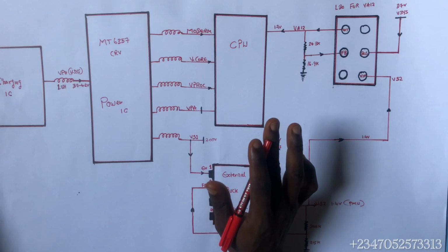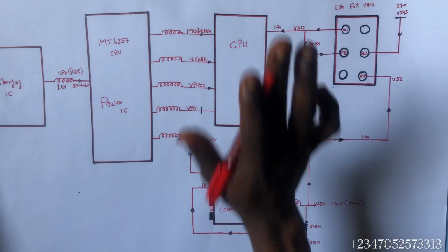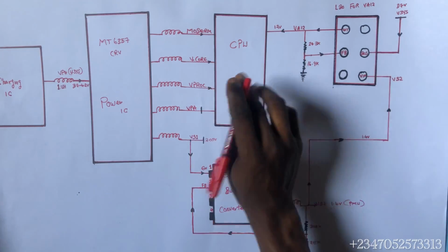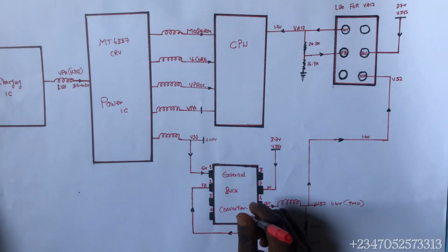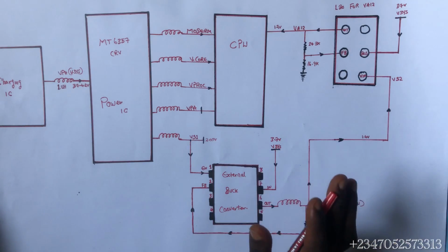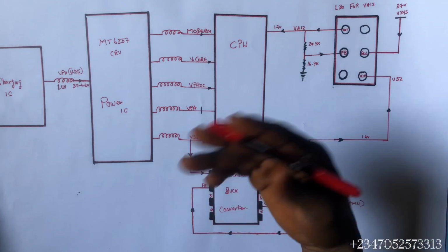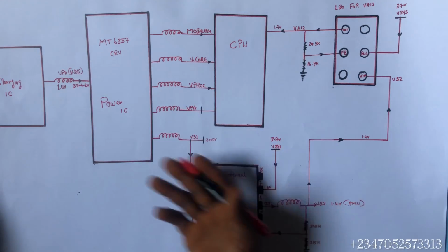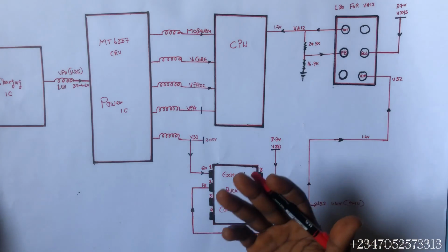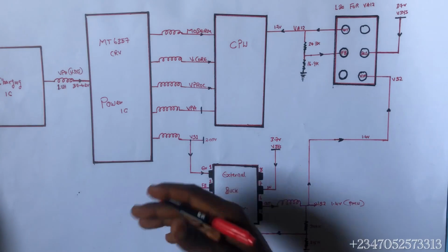The purpose of DC reading is to give you a clue. It will give you an insight into where to start working. Okay, it tells a lot, but don't depend on that. Know the sequence. When you know the sequence of how this IC boots up, my dear, you can figure out, you can trace the fault.